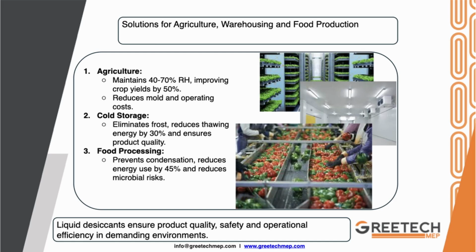One of the most important benefits in cold storage and food processing is the fact that you avoid condensation or freezing, which causes mold and mildew. By circulating dry air within these types of applications, you also avoid the additional cost of defrosting, which is what I mentioned in the previous slide. And by effectively controlling moisture, you prevent the growth of bacteria, molds, and viruses.